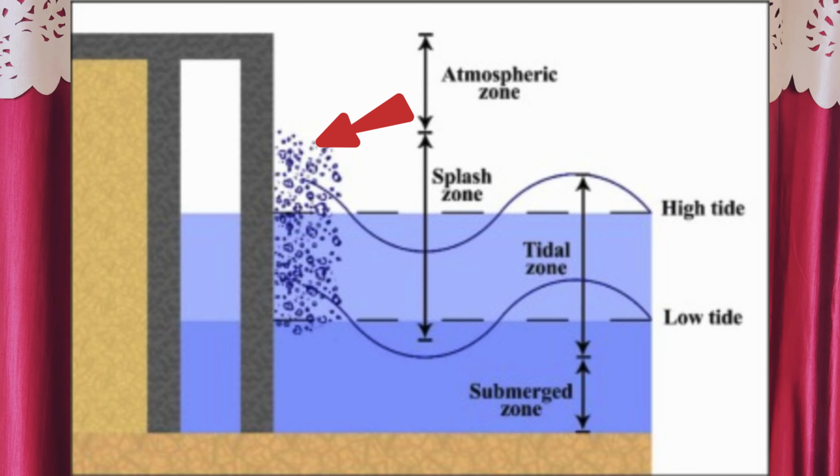You know the marine splash zones, right? Or I will tell you. Marine splash zone is a part of the marine structure that is above the high tide level but gets repeatedly wet due to wave splash, spray and wind blown seawater. It's the zone where seawater doesn't stay permanently but keeps hitting, wetting and drying the surface again and again. And what is aggressive soil if you don't know? Aggressive soil is a soil that can chemically attack and damage concrete, steel or other construction materials over time. In simple words, it eats structures slowly.